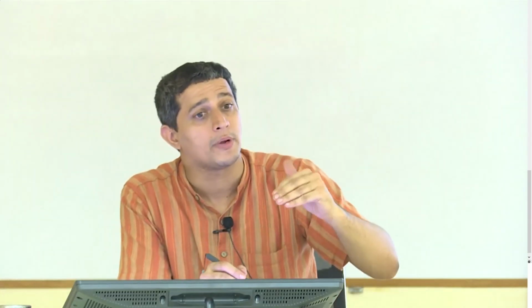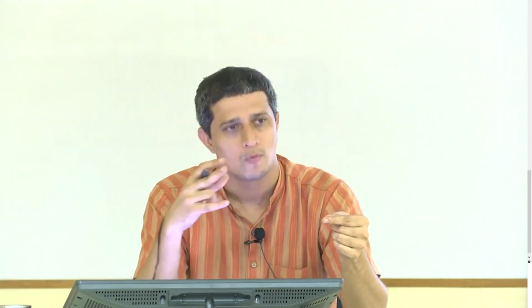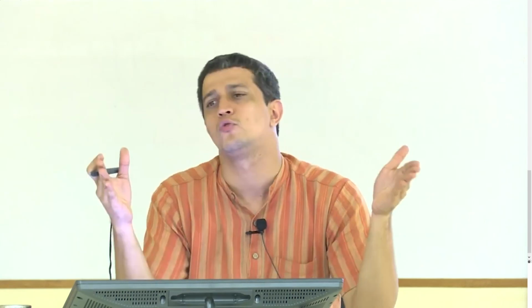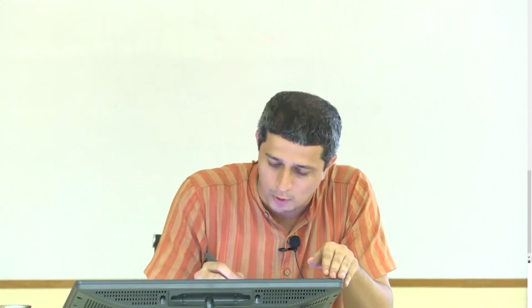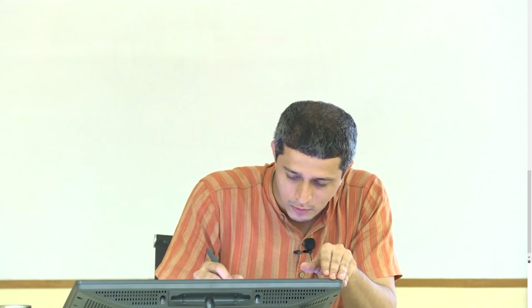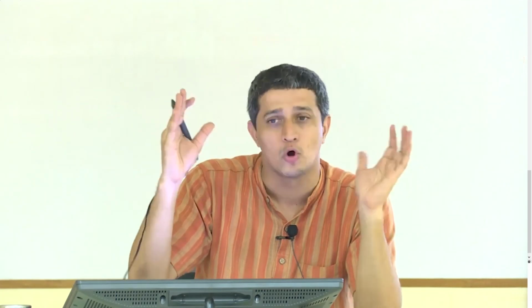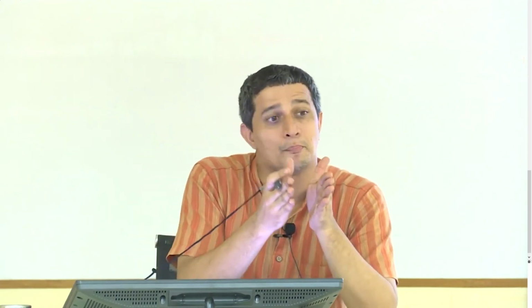The change that is happening after the sampling edge, I don't want it to be captured. I want that to miss. I want it to retain D2 all through. So the point is, this change is T hold. If it changes far away from the edge, then D2 will be captured, there's no problem. The change to D3 will be ignored. If you bring it very close, that minimum time after the clock edge where a change in D will not go through is defined as the hold time.